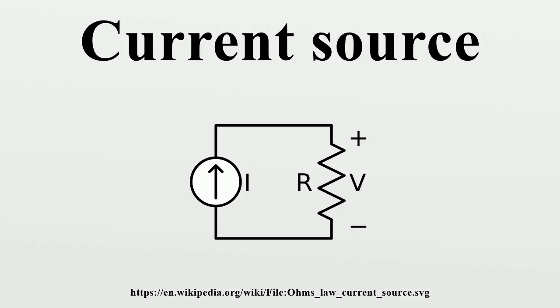As a result, the op-amp inverting input is held at virtual ground, and the combination of the input voltage source, the resistor and the supplied op-amp constitutes an ideal current source with value IOUT equals VIN over R. The op-amp voltage-to-current converter in Figure 3, a transimpedance amplifier and an op-amp inverting amplifier are typical implementations of this idea. The floating load is a serious disadvantage of this circuit solution.